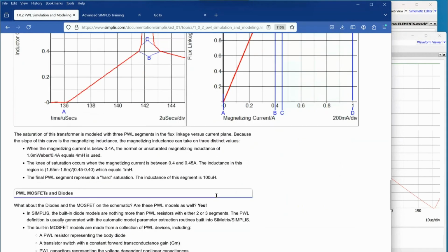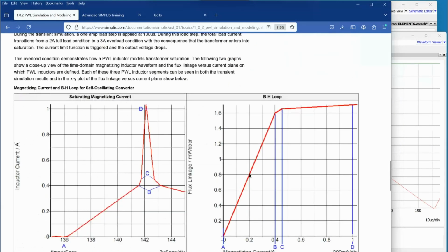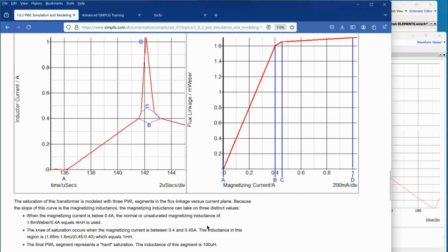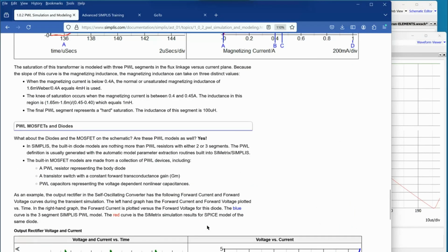You'll notice that it doesn't include hysteresis loss. I said this is proportional to the BH loop, which it is, but it doesn't have the width of the BH loop. To model the losses well is what we work on doing in our magnetics design module, which we have some really good webinars on, but we just won't have time to go into in this course. All right, so that's magnetics, but you can see the piecewise linear characteristics.